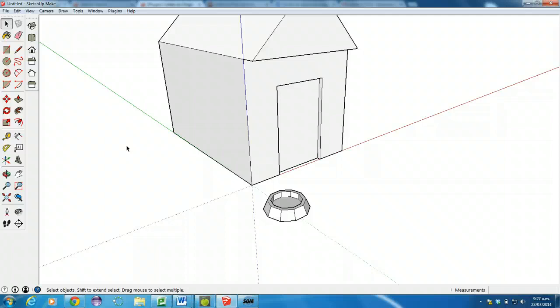It's not easy to undo mistakes in your model. In Blender, 3ds Max, other tools like that, there are ways to fix your model if you make mistakes. So for example, if you've got two vertices that are really close together but not quite touching, in Blender or 3ds Max you can just join those together, weld them together, and essentially make them into one, which should fix most errors in the model. In SketchUp, there's not really any way to do that. You'll have to delete them and then redraw small parts of your model. So it's important in SketchUp to work with simple geometric shapes and get it right the first time.